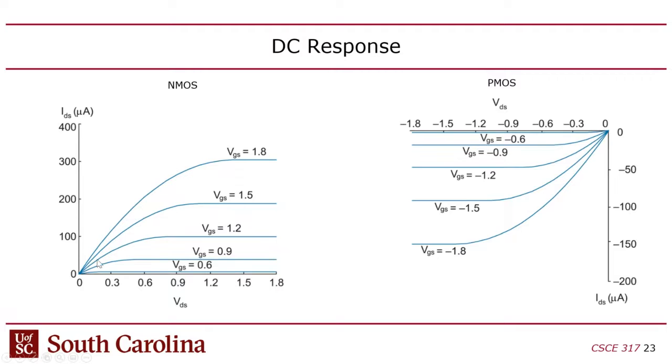Now you might be wondering why the linear modes aren't all on top of one another. I don't know. The slopes in linear mode are slightly different depending on your gate voltage, which is a secondary effect. I've never looked at that. Ideally linear mode is just linear, right? It should have a slope of 1. But clearly, as you lower the gate voltage, the slope changes a little bit even in the linear mode.